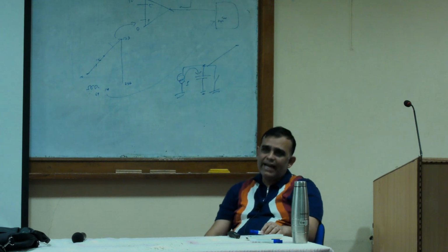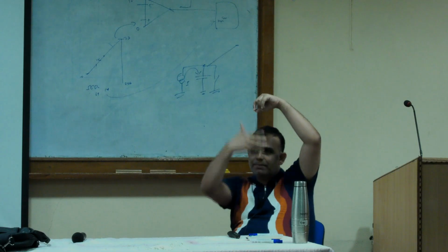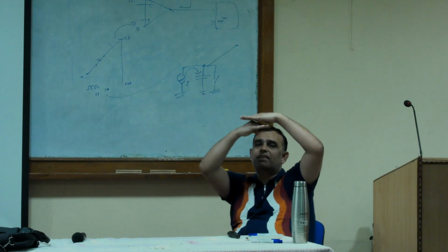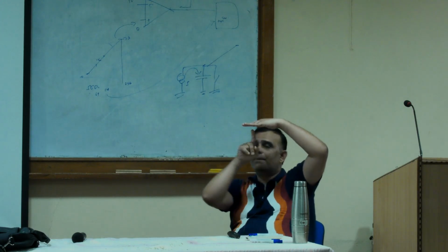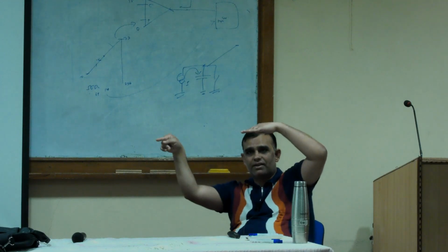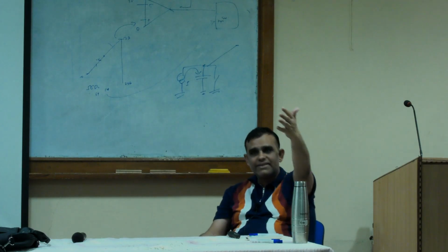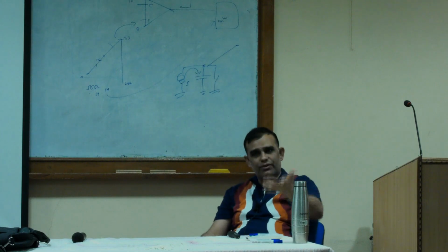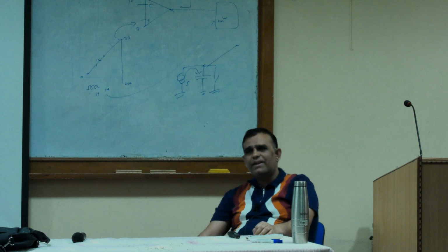But if we do that, the difference between one red pixel and another red pixel is 3 pixels vertically. You have red, a green pixel, a blue pixel, then again a red pixel, so there are 2 pixels in between. But on the horizontal side, every red pixel has a red pixel next to it. So it's non-uniform sampling of the scene. We're taking a red sample, a blue sample, and a green sample of the scene, but it's non-uniform. There has been quite a lot of work on different types of patterns.